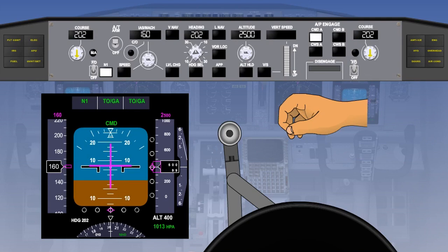The pitch channel of the autopilot pitches the aircraft up to achieve the pre-programmed vertical speed. The roll channel of the autopilot maintains the track that existed at the time the Takeoff Go Around switches were pressed. The objective is to fly the aircraft up directly over the runway centerline. Go Around is a one-button operation to keep the aircraft away from any danger. As the aircraft climbs, the pilot will move the flap from a landing to a takeoff position and select the gear up. The autopilot will not operate the gear or flap.